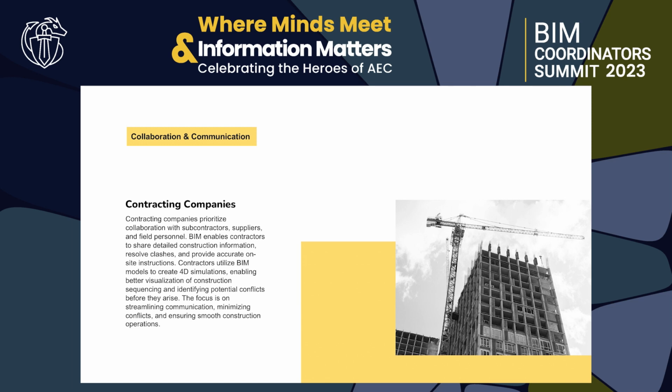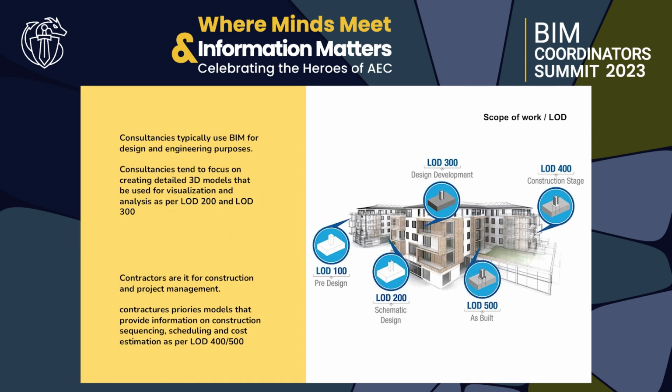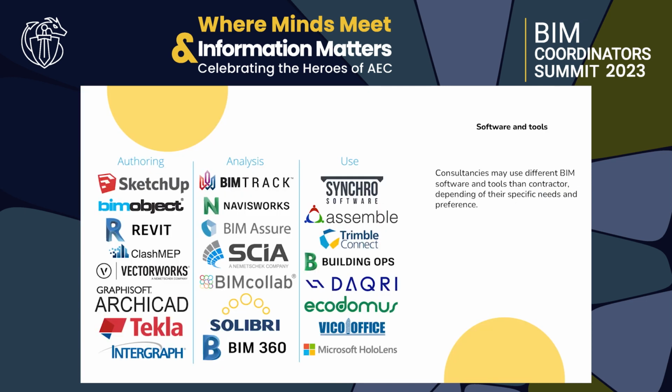On the other hand, contractors collaborate and communicate with subcontractors and suppliers, sharing detailed information to provide accurate instruction on site, minimizing conflicts, and ensuring smooth construction operations. Regarding the level of development, consultants develop models according to LOD 100 pre-concept, LOD 200 concept design, LOD 300 detailed design, whereas contractors work to develop the models according to LOD 400, the shop drawing, and LOD 500, the as-built models.